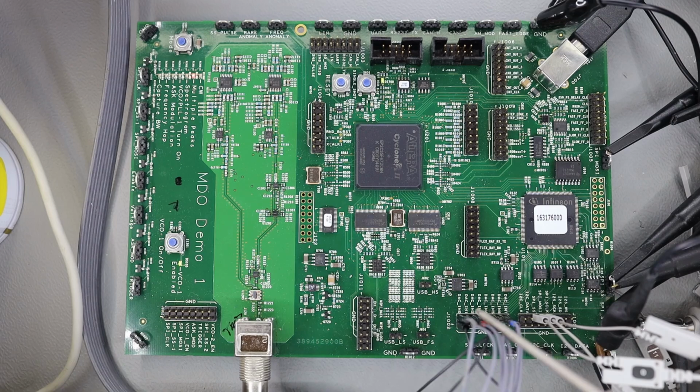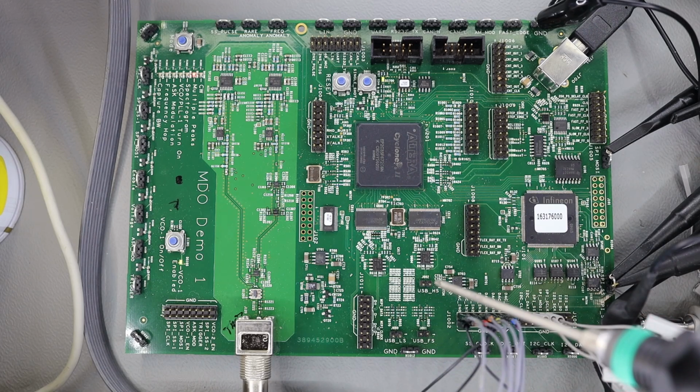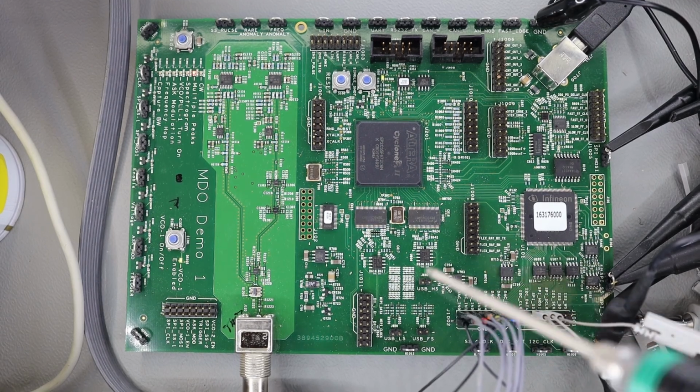These are the DAC, raw DAC data, digital values. On this side you have high-speed signals, for example MIPI, or you also have USB LS, USB FS, and you also have USB HS. Probing a USB HS is going to be interesting. We will need two probes because I do not have any differential probe. So we'll learn about the probing as well, how to deal with a situation where you need a differential probe and you don't have it. So our oscilloscope will help us.